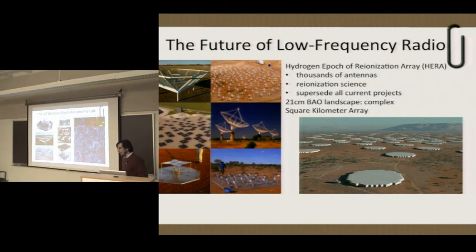An idea we're exploring right now is actually using our full bandwidth to do rotation measure synthesis, which is instead of taking Fourier transforms in linear space frequency bins, binning in wavelength squared, which is the linear measure of how phase is being rotated by these screens, and looking for signals that coherently add through your whole wide bandwidth when you bin them that way. And we're trying to create filters that we can then use to remove those coherently using these 100 megahertz bandwidths, such that we can open up 10 megahertz bandwidths without those modulated signals. And we have to see what kind of suppression we can get from that.